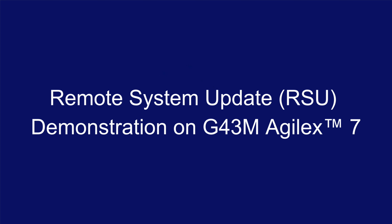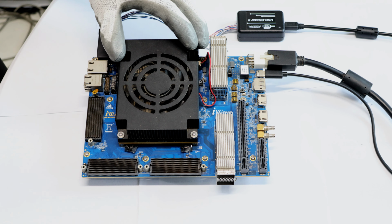In this video, I will be explaining Remote System Update. Remote System Update, RSU, is a feature that allows an FPGA device to be reprogrammed with a new image without requiring physical access to the hardware. Instead of manually connecting the programming hardware, firmware updates can be delivered remotely over interfaces such as Ethernet or other communication channels. This enables bug fixes, feature enhancements, and security updates to be deployed efficiently while keeping the system operational and significantly reducing the maintenance cost. In this video, I will demonstrate the complete remote system update workflow on the Agilex 7 platform.